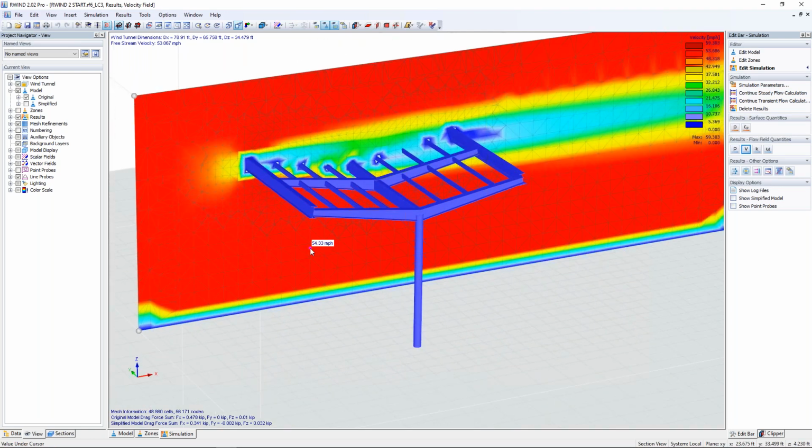But we probably have a slight issue here. We know with this canopy type structure that we likely will have some type of panel on the roof, but we didn't model the panel because it's not so important for the actual structural analysis itself. The problem is that the program only knows what it knows. So we saw the members modeled in RFEM, it brings only those members here in RWIND.